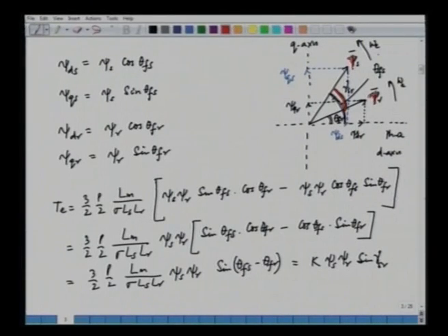That angle between the rotor and stator flux, gamma sr, is something similar to the torque angle. So, if I can change the angle between the two fluxes, I will be able to control the torque. Now, with this background, we can say that torque can be controlled in two different ways.